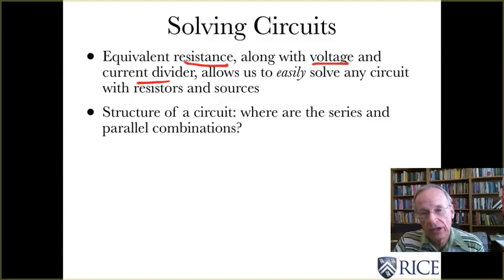And notice we solved that circuit having the load resistor on it without ever writing KVL, KCL, or the VI relations. We just wrote down the answer. That's really very, very nice. So the whole idea about being able to solve circuits easily means seeing the structure, what's in series with what, what's in parallel with what, and finding the equivalent resistances accordingly.